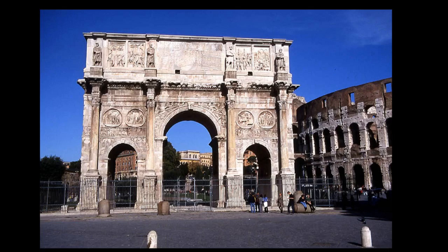Especially the late 19th century architecture uses these combinations, and what you can see here is a triumph arch in Rome next to the Colosseum. On the right side you see the Colosseum. And here you see what I was talking about, seen on Robert Chitham's proportion system: a Greek column, here the highest order again, the Corinthian order that you see here in the middle, with an entablature in the right height, so it fits to the rest. Actually this line here is a bit irritating because it makes the entablature look even higher, but actually this line here doesn't really belong to the proportion system.